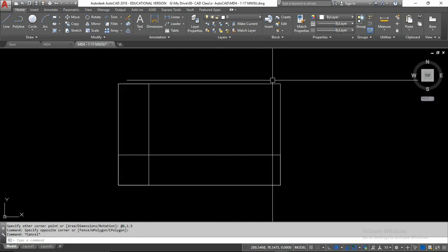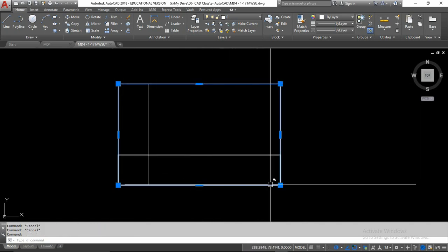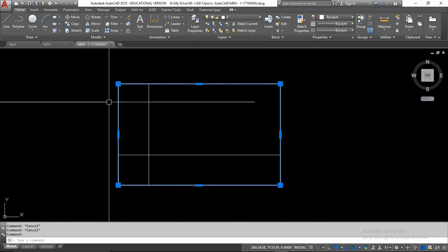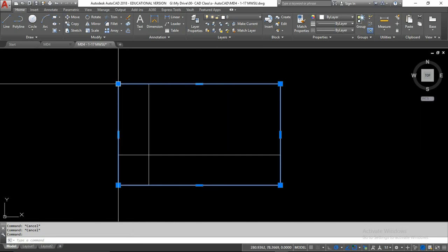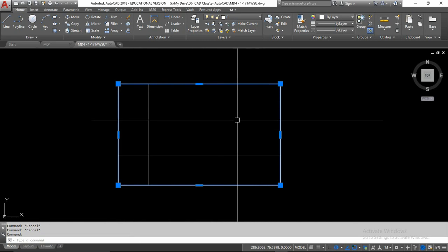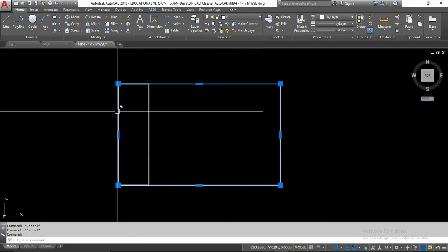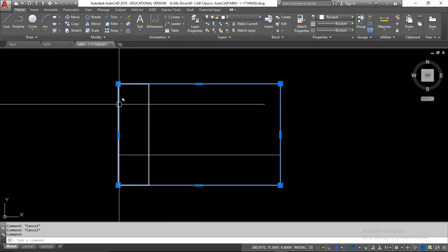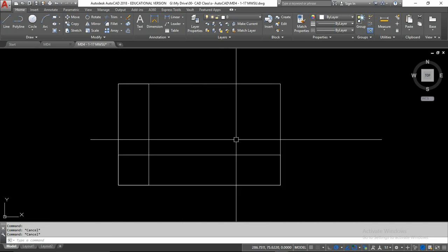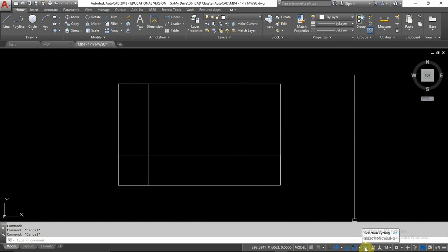This is a nice thing about using polylines, so that I don't have all these things over the top of each other, or having to select, well, which line is it? The line of the big rectangle, the line of the little rectangle. That's one nice thing about using polylines, because they're not all broken out and individual, and then wondering how many I have here. I told you before in the settings, if you wanted, you could turn on what's called